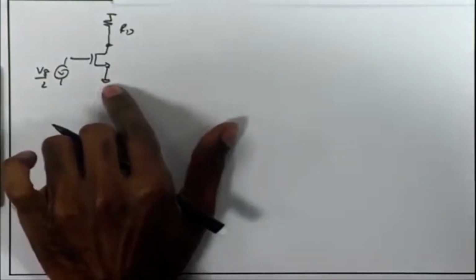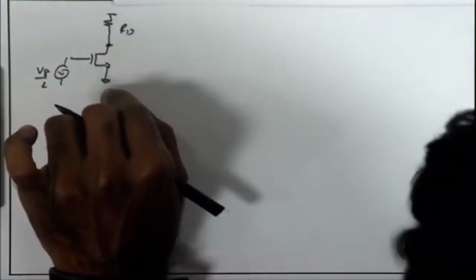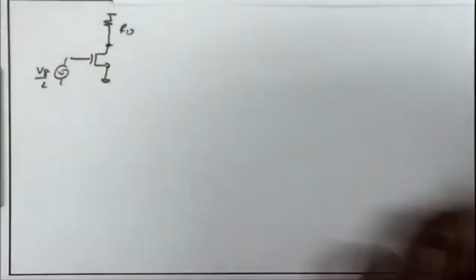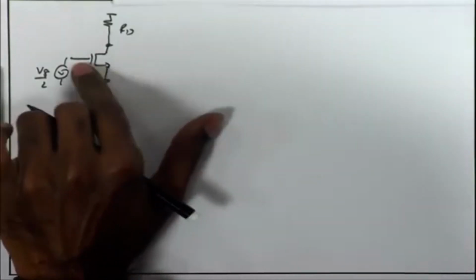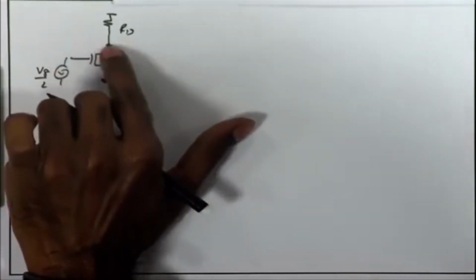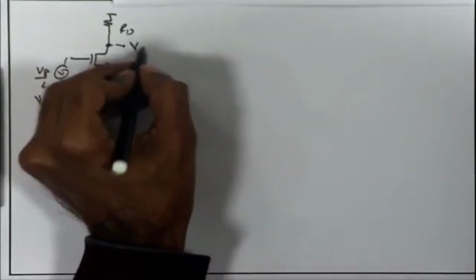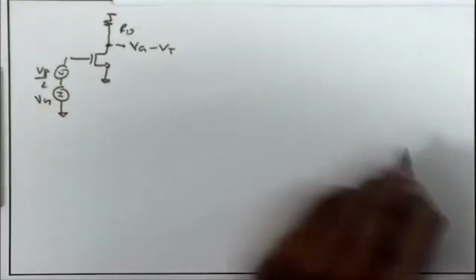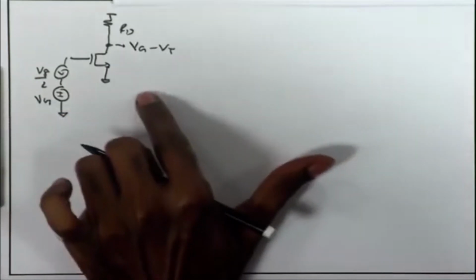Something is going to differ, and that is our swing analysis, and we also need to address what is going to happen to our noise analysis. Is the noise analysis going to remain same, or do we need to have any difference? So, from the point of view of DC, once again we know that there is a bias current coming over here, you have some DC gate voltage over here, and the minimum drain voltage that you can have is going to be, suppose there is a DC voltage capital Vg, there is a DC bias point for both the sides, and the minimum output voltage you can have is again going to be Vg minus Vt, but this Vg is also going to be determined by some other constraint, and that is given by the constraint produced by the current source.